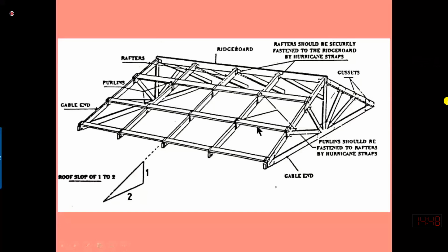In this way, the purlin cannot bend in the lateral direction. In our beam design topic, you will learn that if a purlin or a beam can bend in the lateral direction, lateral meaning horizontal instead of vertical, then it reduces the capacity. If the beam is restrained from moving in the lateral direction, then we can achieve its full capacity. We will learn this in detail in our beam design topic.